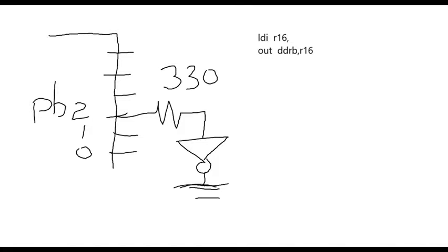The second step is to turn on the LED, which will be very similar. You're going to load R16 with a number. Let's get rid of that comma though. That's not good. There we go. And put the comma here. Then hit enter. Then you're going to say out to the port B, comma R16. Well, that's the second step, but neither step is complete.